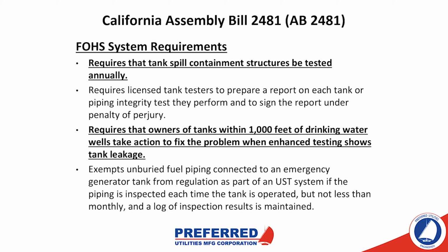So those are commonly referred to as annual certs. The second thing is that AB 2481 requires that owners of tanks within 1,000 feet of drinking water wells take action to fix the problem when enhanced leak testing shows tank leakage. This is often why a lot of sites have SPCC plans done prior to the installation of the system. SPCC plan, for anybody who hasn't heard of one, is a spill prevention, control, and countermeasure plan.